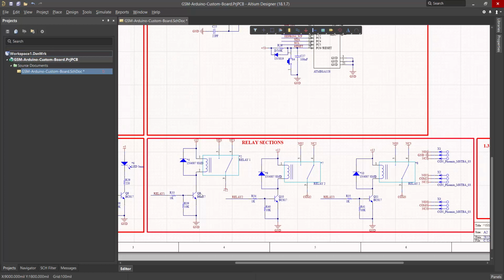For controlling these relays, we need a 12-volt source, so we use a transistor circuit to control these relays. Also, we have here a freewheeling diode for protecting our MCU pins from damage. I will discuss it later. I'll tell you how it works.